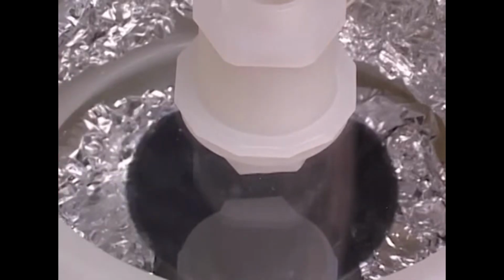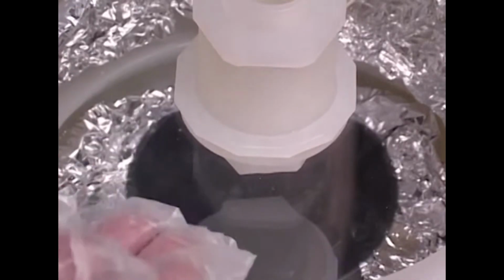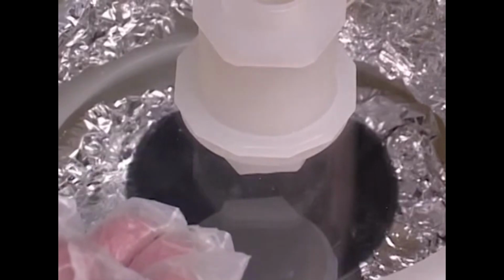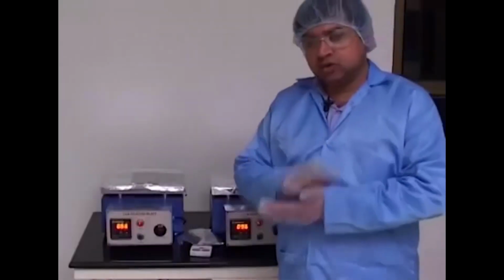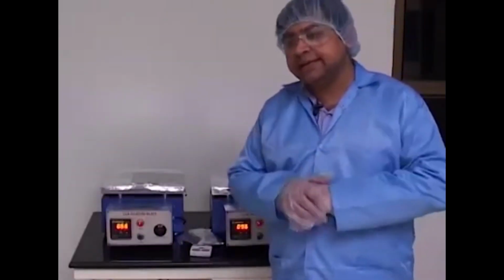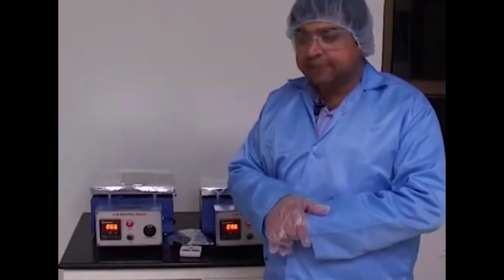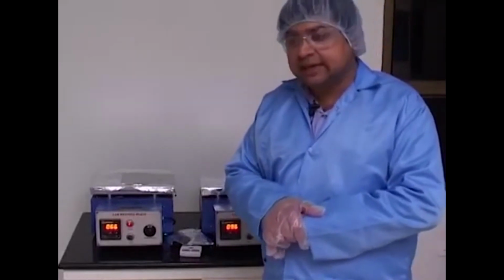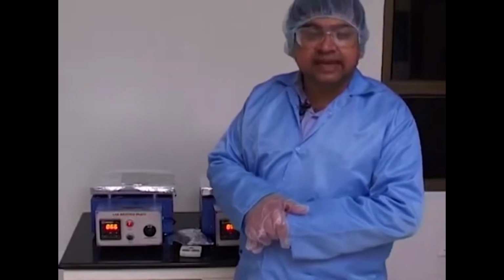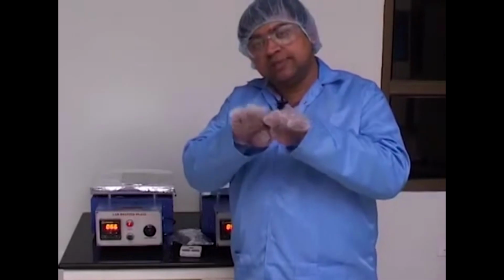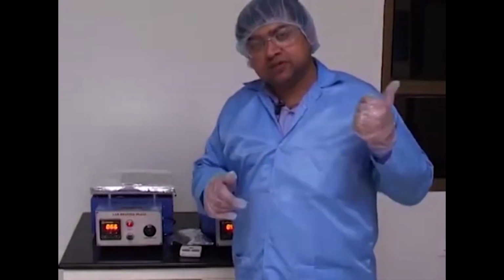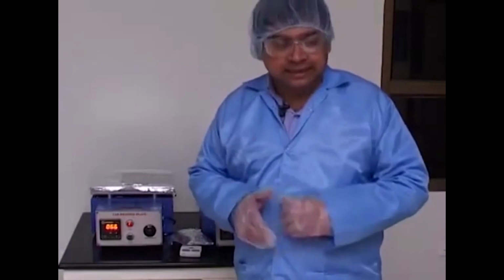And the moment the resist is spin coated, we also need to take this for the twin step heating process, which I am going to describe in a little bit. So the resist, as I told you, needs to be heated, and one of the purposes why heating needs to be done is that there is a solvent which is really a carrier solvent for the resist. It has an epoxy resin which is dissolved in a carrier solvent, which is actually cyclopentanone, and the purpose is to transport the epoxy uniformly over the surface of the wafer in the spin coating process that we saw in the last step.